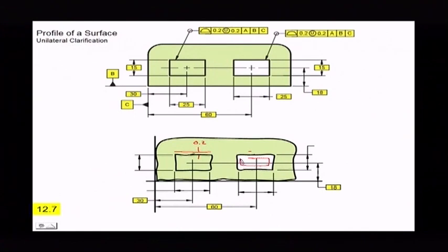So be careful, because what that U in a circle is going to do, that amount is going to make the hole smaller. So what you're going to get, if you looked at your mins and maxes, is you see how the unilateral out will make the pin bigger, and the unilateral out will make the hole smaller. So just be careful, a little bit of clarification there. It's not unilateral out of the line, it's actually out of the material.